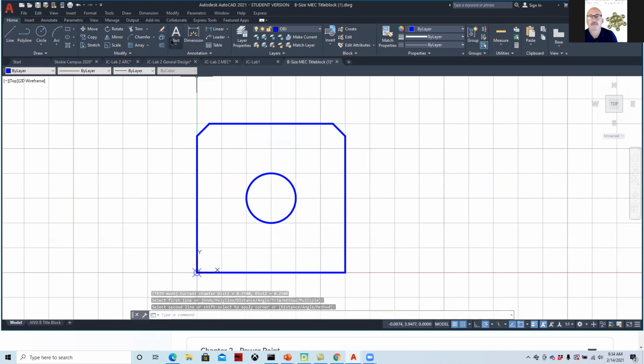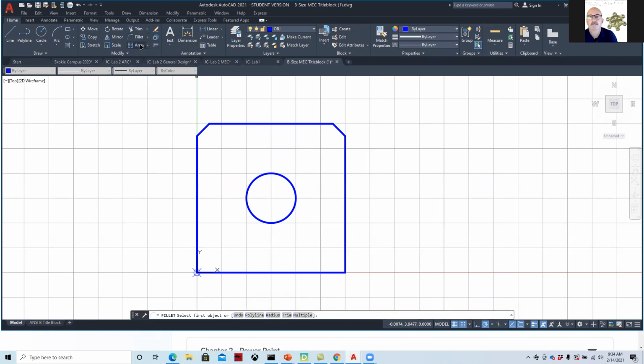And then if I put a radius in here, similar commands are like grouped together. And so fillet and chamfer are very similar, so they keep them together, but they work the same way. You have to modify existing geometry. Radius 0.25, great. And then I'll click this line and this line, repeat, click this line and this line. And then we want to use layers.